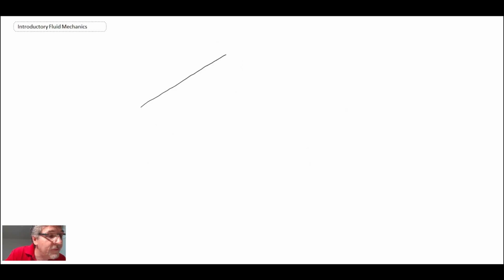So here's our plate. And let's say this is our center of area located right there. And recall that is where our coordinate system begins from. We've defined the coordinate system there. And if I sketch up, we said that the angle of the plate was theta. So if we are at a location y, and remember, the coordinate system begins at the center of area, at this location, the center of area, we know that we have HCA. That is the depth at the center of area.